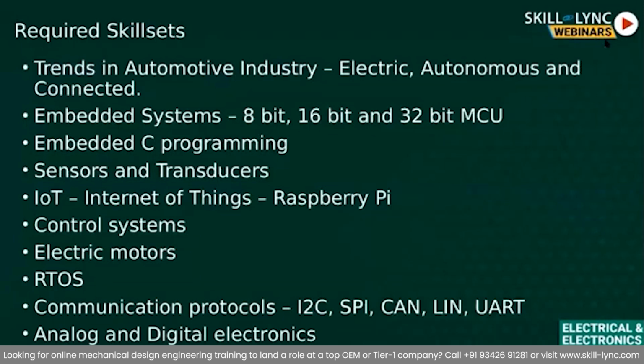You have embedded system, which is nothing but a microcontroller. And as you all might know, microcontroller can handle only low voltage. Some microcontrollers can handle up to 5 volts, and some microcontrollers can handle up to only 3.3 volts. So when you have to integrate microcontroller to a sensor and ensure the car moves or car performs some action, you have to provide more voltage. But your microcontroller can provide only less voltage as an output. So you need a signal conditioning circuit that can enhance this output and achieve the objective. And that is why signal conditioning design experience and knowledge is very important when considering automotive electronics domain.